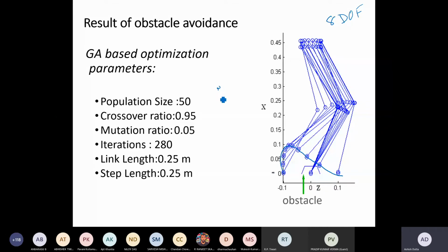So when we are walking, if you notice, please notice somebody else walking, or look at yourself walking in a mirror. What you'll note is that this leg goes up like this, it comes down like this, and then goes forward. This is called an S curve, and this is an optimal curve. So when human beings walk, we first take up our feet, it goes up like that, then it comes down, remains parallel to the ground, and then comes to stop. Okay, this curve is called an S curve, and it has been found that all human beings use this trajectory only, and it is proved to be energy optimal.